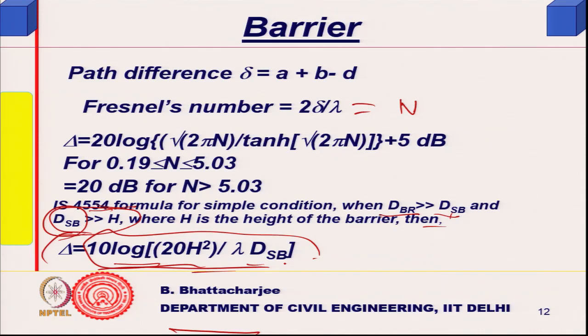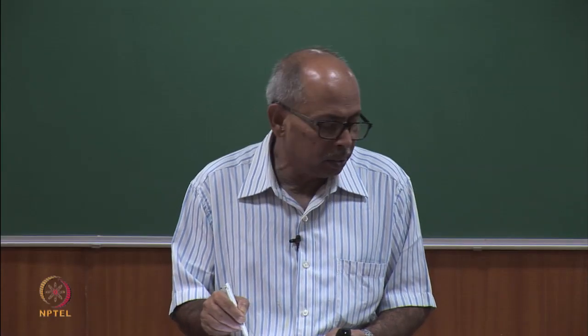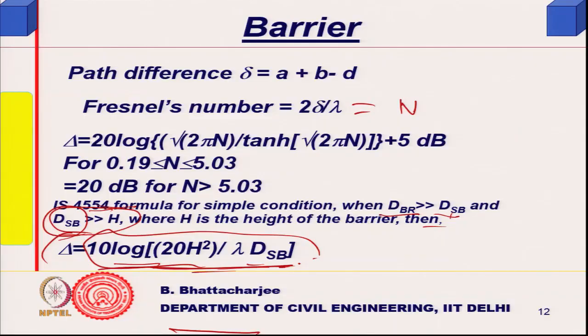So, this will be, in our previous case, 20 dB. Previously it would possibly go to 20 dB if we calculate out the path difference, because this is for the case that we talked about. But generally one can use this; there is a more general form. You have curves plotted, and from that they have derived this equation. So one can actually derive barrier design using this.